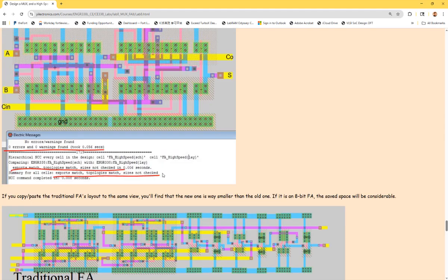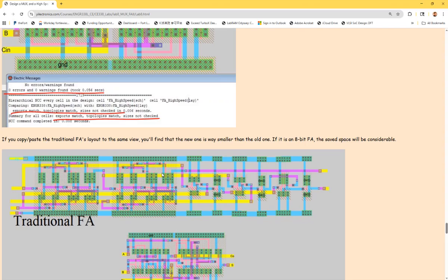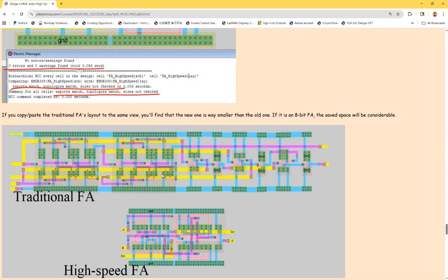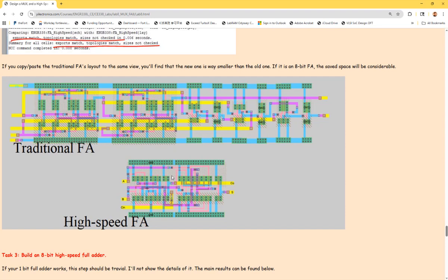Okay? So actually, with the Cadence and Synopsys tools, whenever they are doing synthesis of very large-scale integrated circuits, they won't be able to optimize that for you. This only can happen when you manually do it with the AOI logic by looking at the logic expression, simplifying everything down to a shorter logic expression, and then designing this layout manually. The tool cannot do this for you.